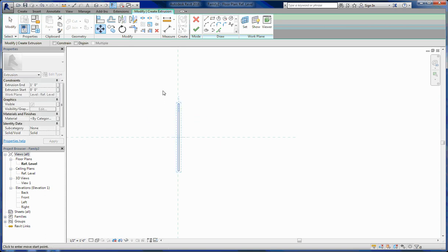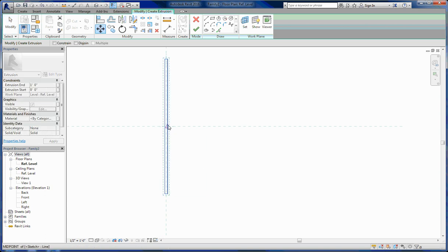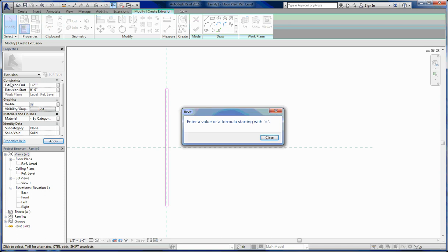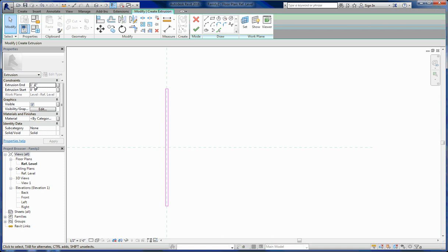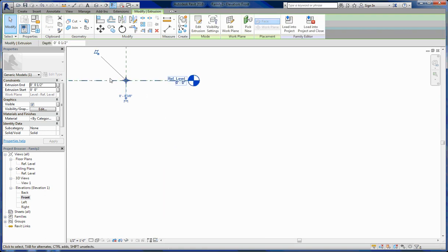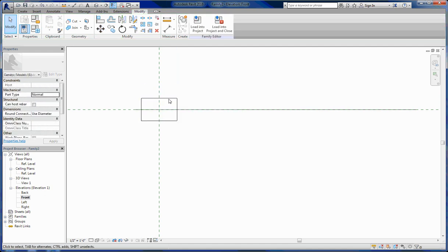And then I'm going to center this on this entire thing. So let's make sure that this is all locked in place on the center there. So I'm good that direction. And then we'll make these like a 1/2 inch deep. Okay, there we go. And so I'll hit that, and then I want to go to the front and back. I'm going to uncheck that, and then I'm going to move this down so that I am centered on all of that as well.